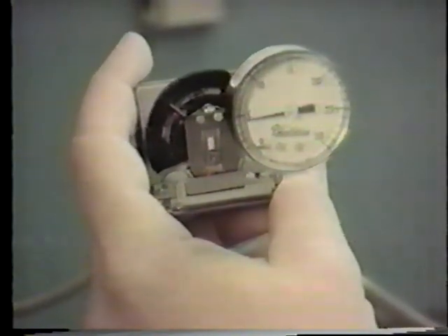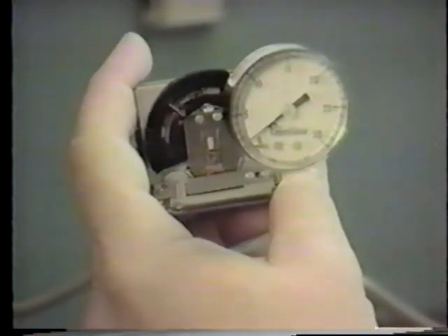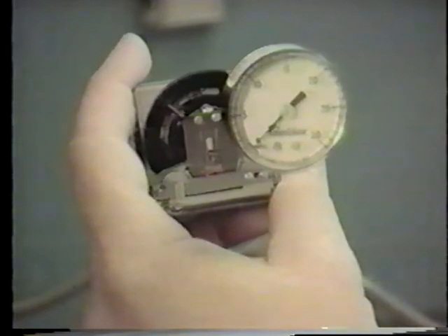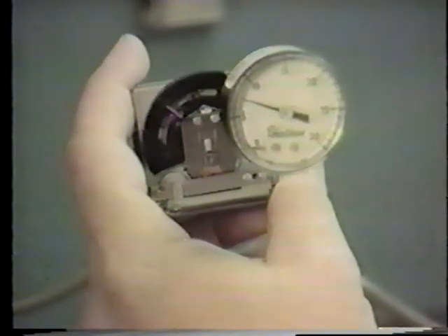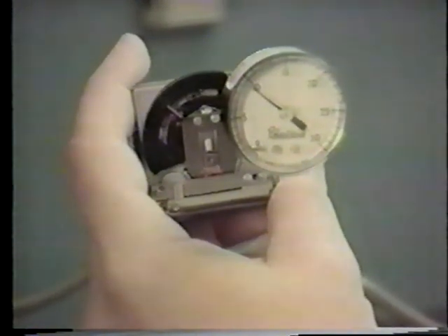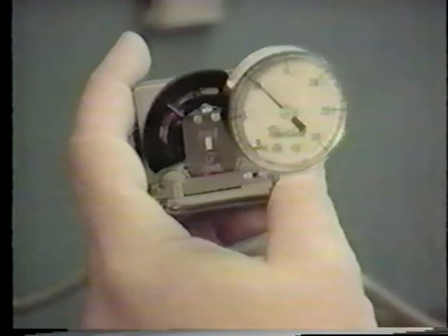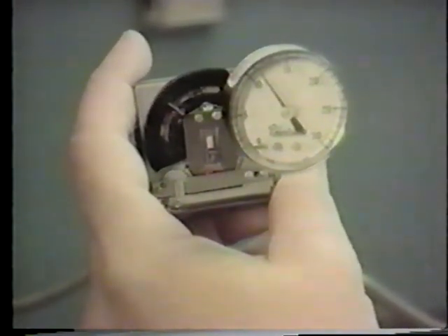As the main air pressure is raised past the switchover point, the branch line pressure should drop to 0, then return to main air pressure when the main air is lowered past the switchover point. The calibration of both day and night settings should be rechecked after any adjustment to the changeover set point. As we mentioned earlier, the complete calibration procedure for all day-night thermostat models can be found in the 2214 series